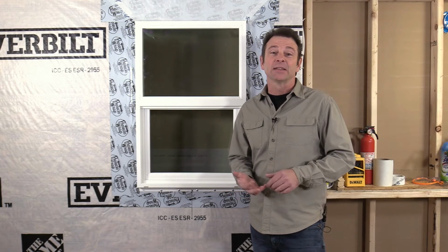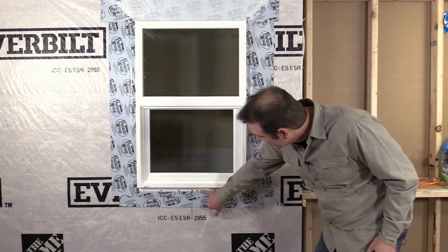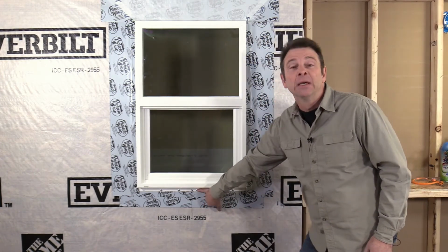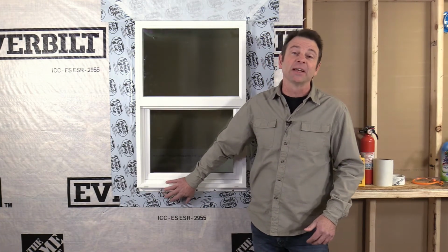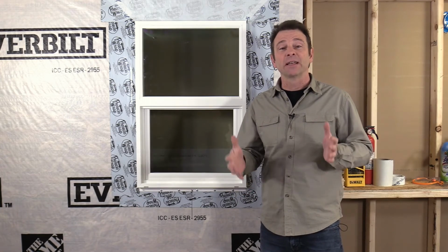Generally, they will give you a screw or a nail option, and they will even get into the sizing of those as far as the length of those fasteners. Here we've used a modified truss head screw. I've also seen roofing nails spec'd, and this particular set of instructions gave either option, both as a 2-inch length for the fastener.